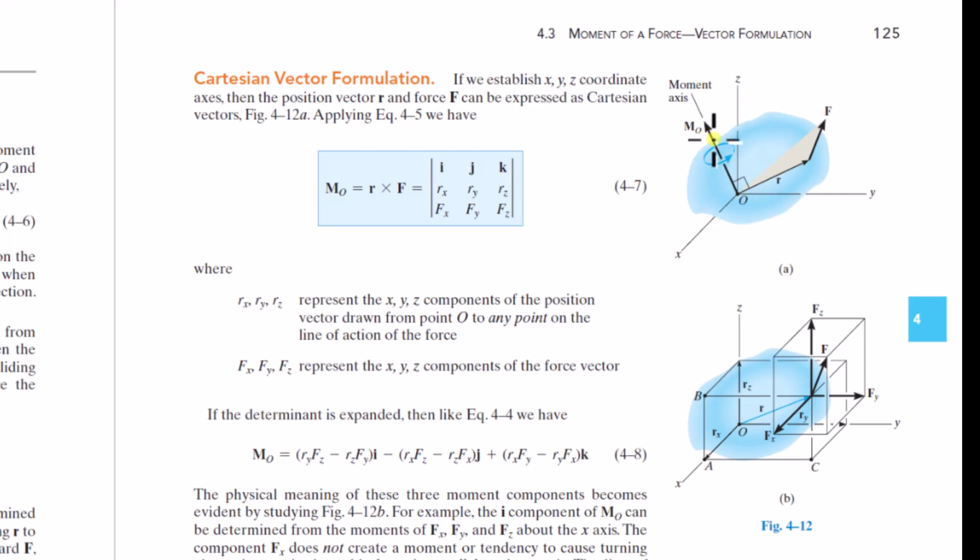And so now you might say, well, this is still a sliding vector because I can slide this moment vector, and the moment vector is not changing. And really, no matter where I apply this moment vector along this line of this axis, it's the same rotation effect on the body. That's true. But when you think about whether something is a sliding or a fixed vector or a free vector, you have to look at the full picture, the full context.